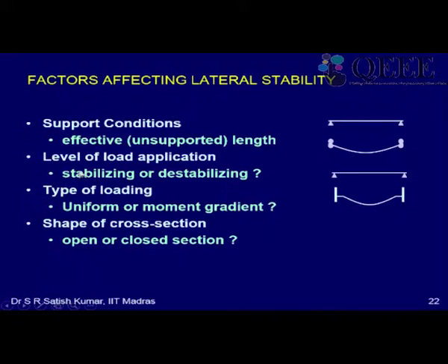if the load is on the top flange. Okay. So level of load application, if it is on the bottom flange, it's called stabilizing. If it is on the top flange, it's called destabilizing. Okay. So that is the major factor which affects the critical buckling strength of beams.